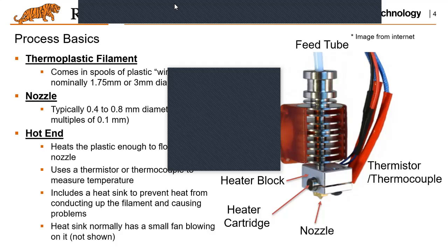Oh, that's a good question. I think definitely some of them you certainly can do. For example, using sandpaper to smooth it is definitely possible. And also paint. Basically, you just purchase some cosmetic paint and paint it, right? For some other ones like solvent vapor, that's for ABS material, which is not the one we use in our lab.